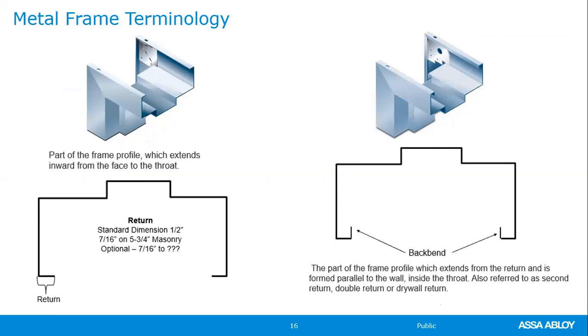Years ago, our more common wall size was a 4 7/8 wall. That was a 3 5/8 metal stud, 5/8 drywall on each side. So they accommodated that, which was the most common. We have not changed that in the industry as a whole. So you want to be aware of that.